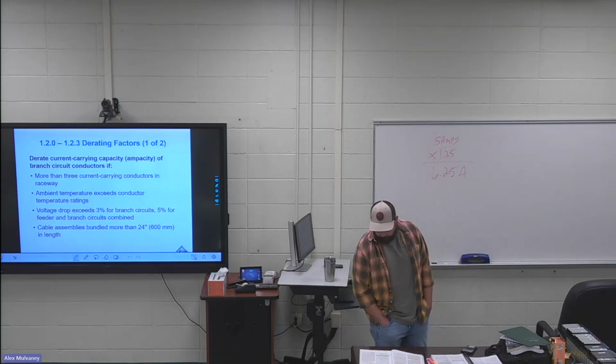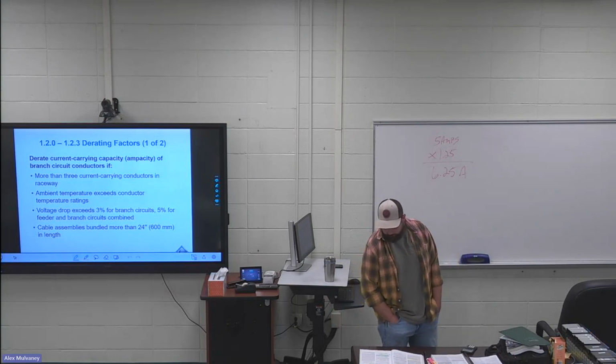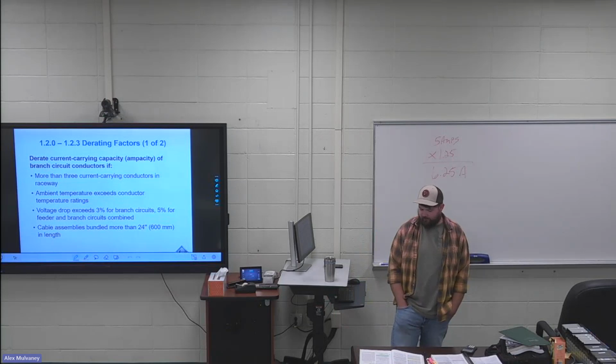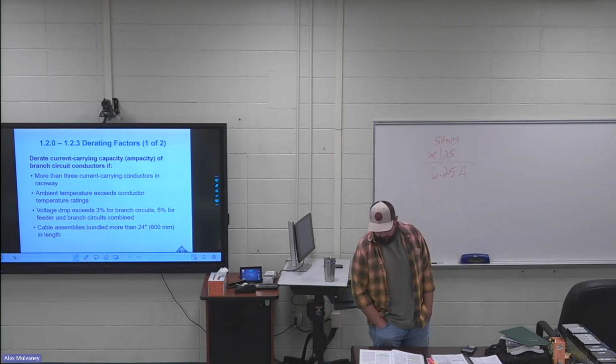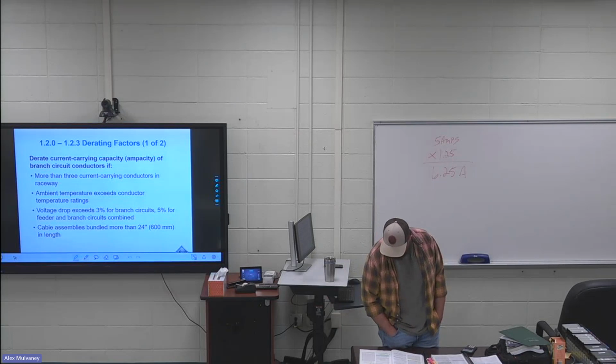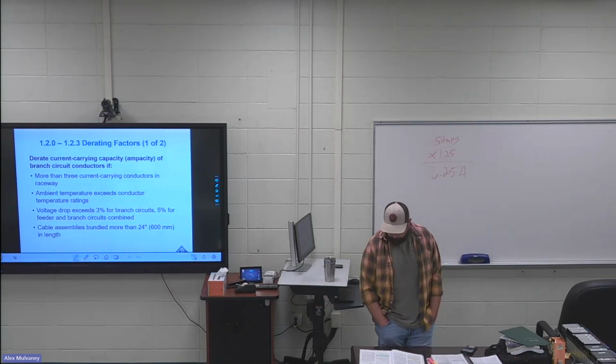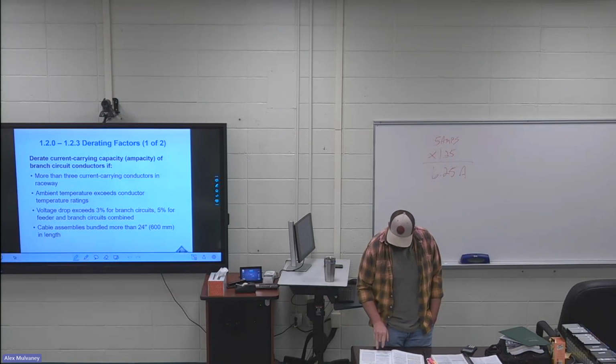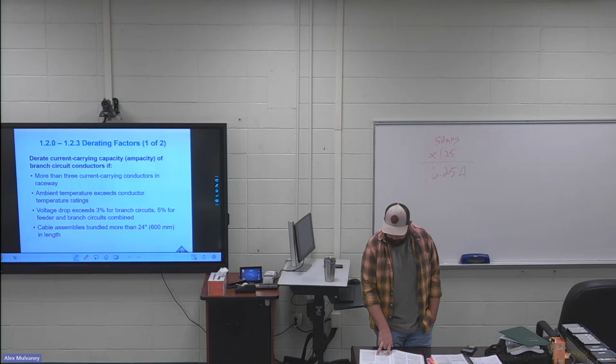Page 5, voltage drop derating for single phase circuits. The entire first paragraph is highlighted. NEC section 210.19(A) informational note number 3 states that reasonable efficiency will be provided by branch circuits in which the voltage drop for the branch circuit conductors does not exceed 3% at the farthest outlet, and 5% for the combination of the feeder and branch circuit distance to the farthest outlet.